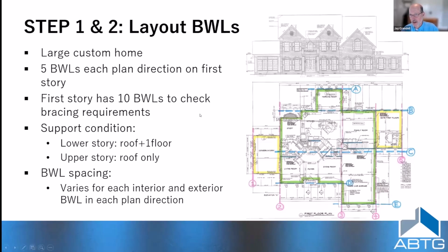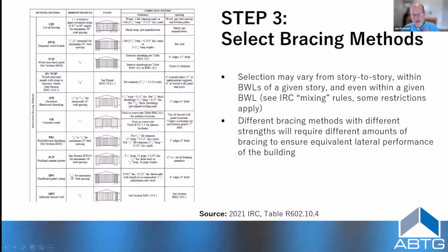But there's a case where you might have many wall lines through the depth of the buildings. Some of them are separate fire separation walls, but only 2 major wall lines running down the sides of the buildings, even though they'd be individual walls in terms of anchoring them, because you've got fire separation between one unit and another. Viewing it as a single building is the way the loads are going to actually happen, and it gives much efficiency in your design and applying the prescriptive provisions. It's a little trick there.